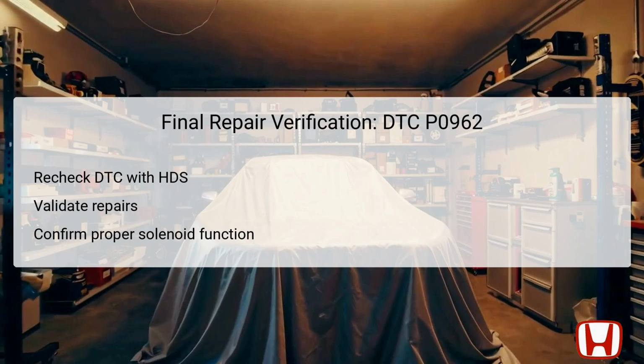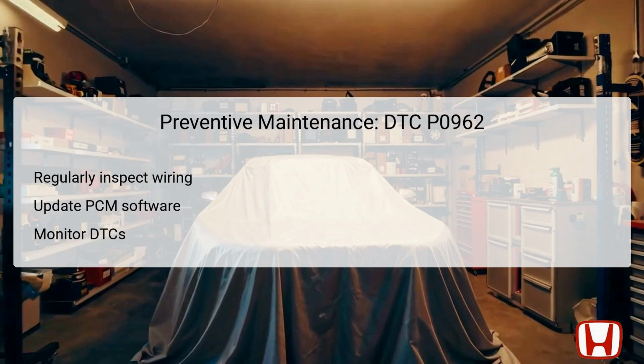Preventive maintenance plays a vital role in ensuring the longevity of the CVT system and avoiding future occurrences of DTC P0962. Regularly inspect the wiring harnesses and connections to the CVT drive pulley pressure control solenoid to ensure there are no signs of wear or damage.